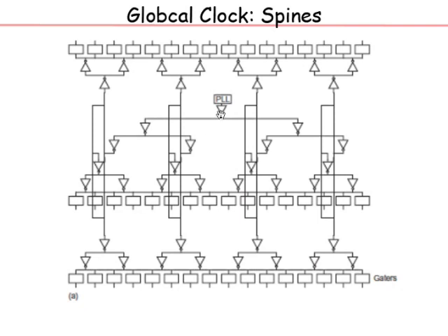Because if you see out here, from here it comes here, and then from here it is sent to this, and then back to this at the center. They don't tap it from here, they tap it from here. So there's extra delay because from here to this there's extra wiring delay. So to excite this spine, they don't tap it locally, but they get it from this side. That's why they're matching the delay from the PLL to all the three spines, and within the spine, because it's horizontal and excited spatially from all along the horizontal simultaneously, the delay across the spine is also kept very small.